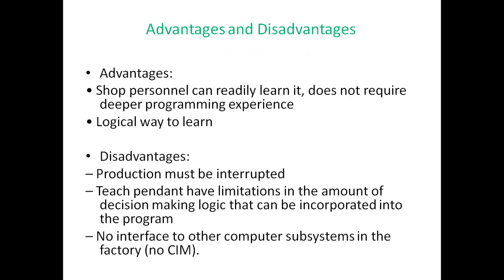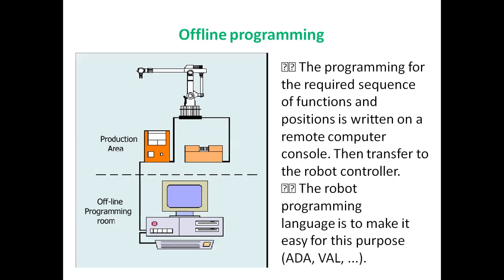Talking about the advantages and disadvantages, the shop personnel do not require deeper programming experience, and there is a logical way to learn. The disadvantage is that production must be interrupted. The teach pendant has limitations in the amount of decision-making logic, and there is no interface to other computer systems in practice.